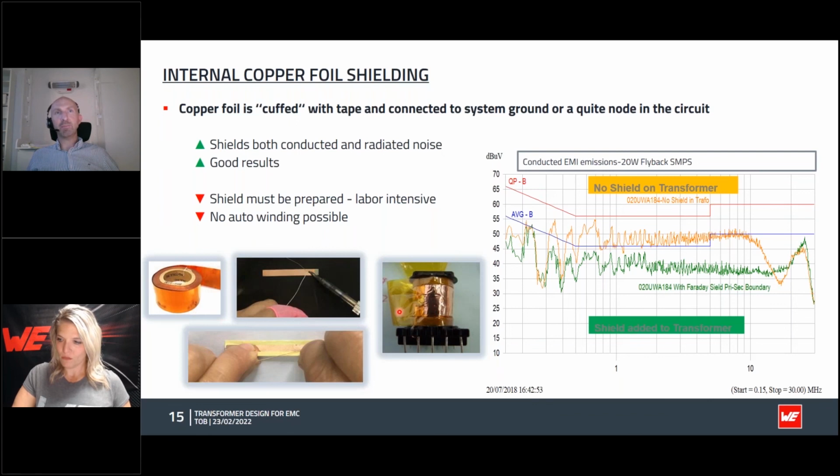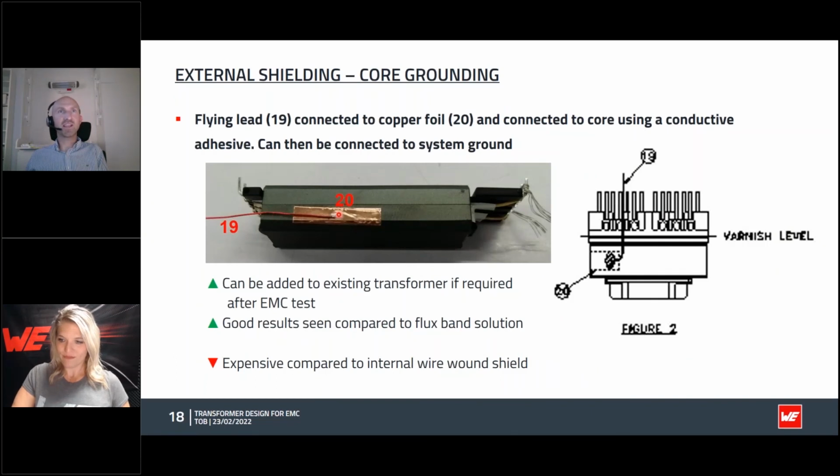And then when you stick on a little bit of copper foil or copper tape onto the core, we're talking about high frequency here, so even if the adhesive is not conductive, but we do use conductive adhesive, which helps as well to lower the impedance, there will be a capacitor between the core and the foil, and so currents in the foil can pass capacitively into the core. So at AC the core can be conductive and will be conductive.